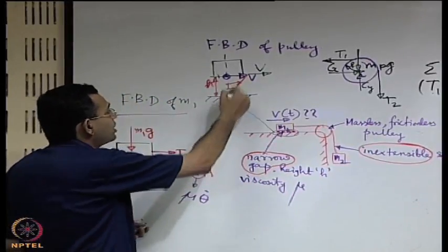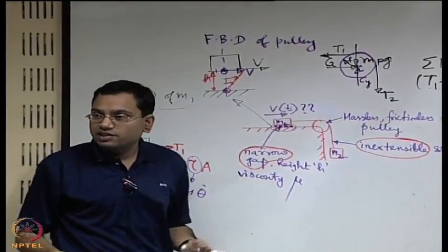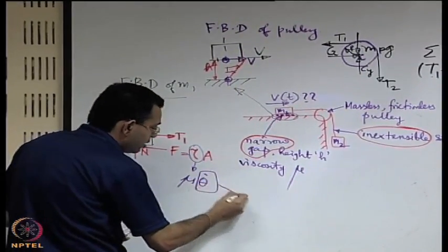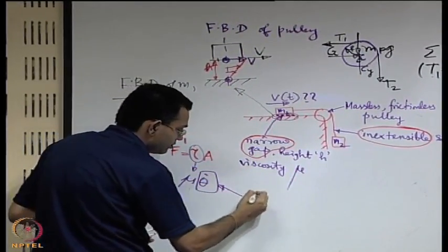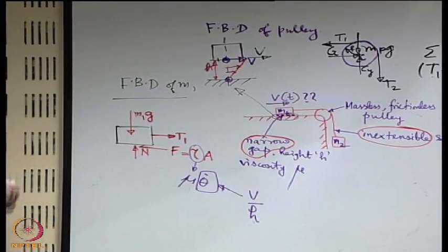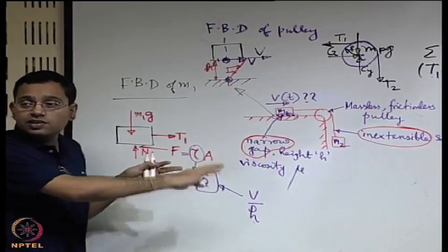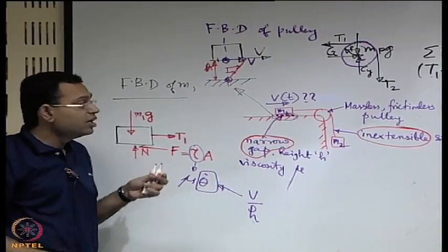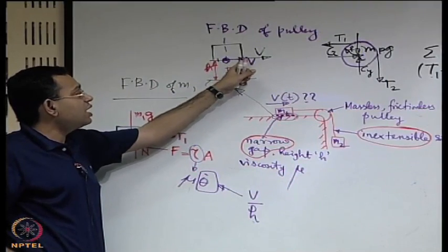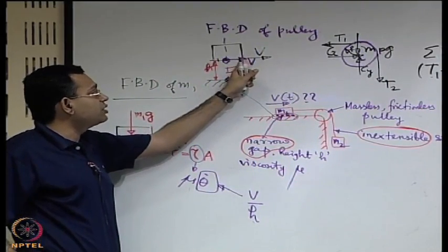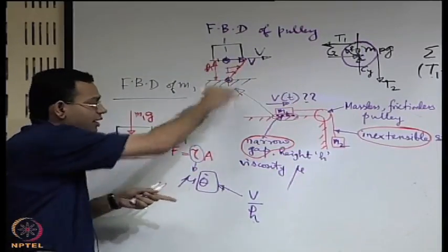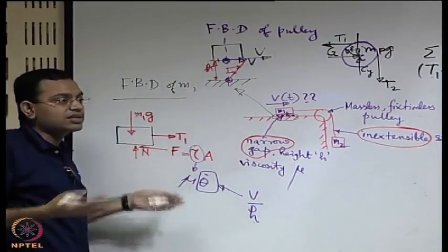So, if u versus y is a straight line, du dy is a constant. So, this for our present case will become v by h. So, remember what are the approximations or simplifications which have led towards this. If this is not a narrow gap, it has to be the rate of change of u with respect to y at the interface between the block and the fluid, not anywhere, but since now it is a straight line, it is as good as it is anywhere.